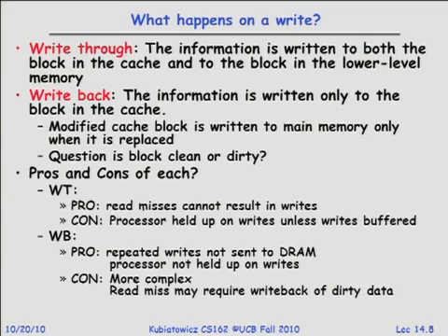Yes, there is a form of a bitmap as to which cache lines are dirty, not always which bytes. Can a process choose whether or not it wants information cached? Yes, processors usually have special loads and stores that say don't cache things. That's often available.